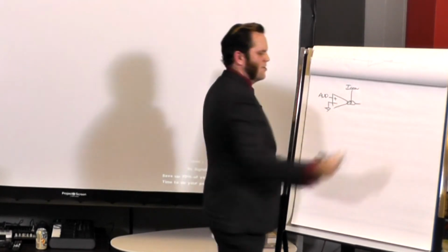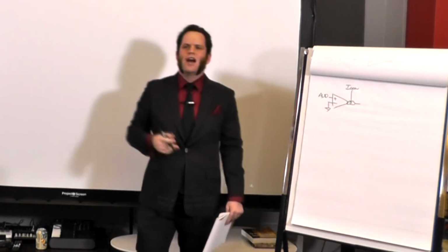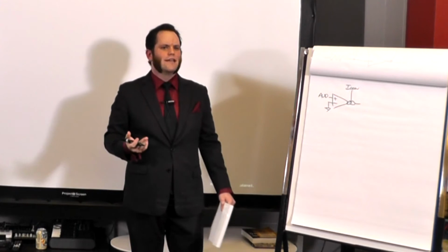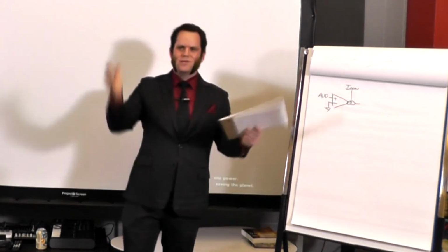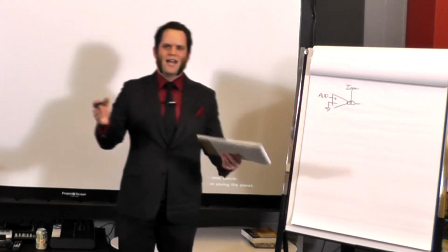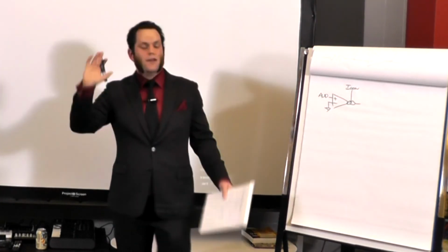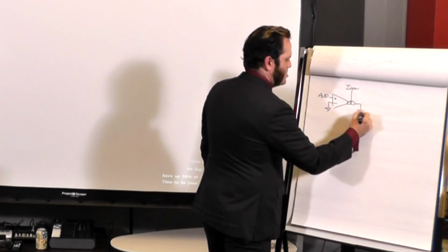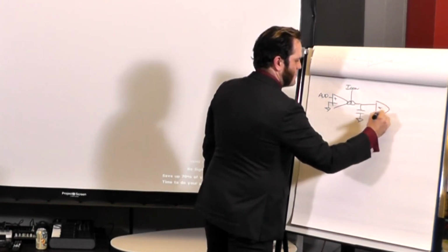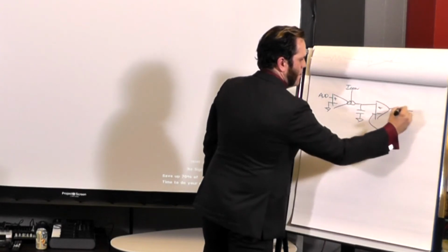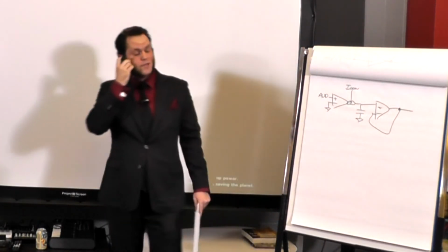And hey, look, we're getting a current output for a voltage input. What does that look a lot like? A resistor, right? Like Ohm's law. We have a voltage, we have some thing, we get a current out. Cool. We can now use that to charge up this capacitor, and then that acts like our very basic VCF.